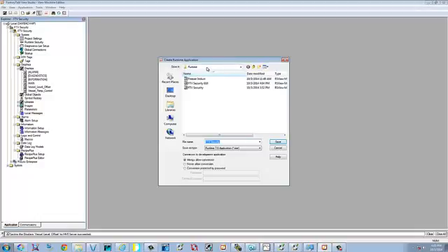It will save it into its default directory, which would be a runtime file. And then we're going to select what PanelView firmware you have. So in order to save a PanelView project so that it'll work correctly, we need to find out on the PanelView by going into your terminal settings and going to About the ME Station and find out which version you have. The one that we're going to download to is running 5.10.